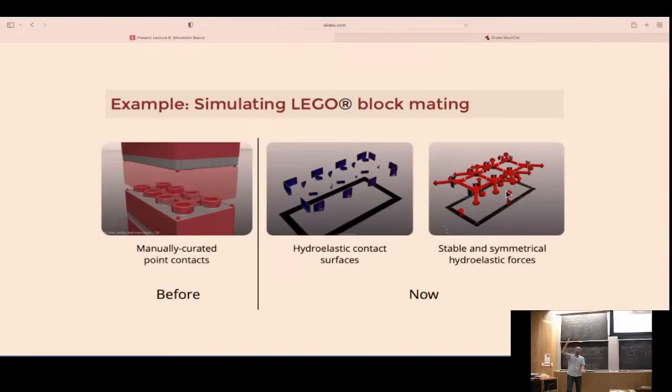I'll make those work this time step, and then the next time step, I'll pick another 10. And that 10 is a magic number, right? And in net, it kind of looks like things fall and separate, and that's all good. But it's not very accurate. And the contact forces, you'd see, would go beep, beep, beep, all over the place, and they'd be missing in some places or whatever. So the real test is if you can visualize the contact forces and they are just sitting rock steady, then you've got a strong numerical recipe behind it.